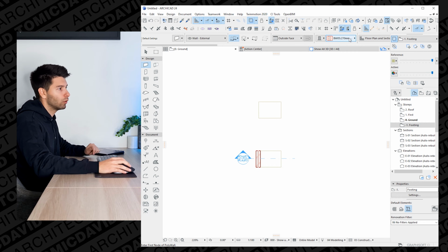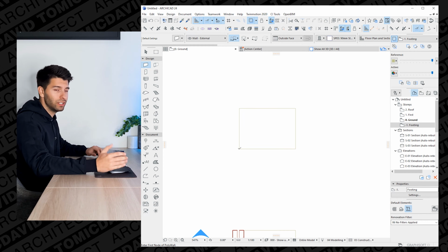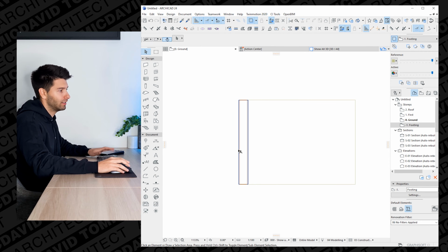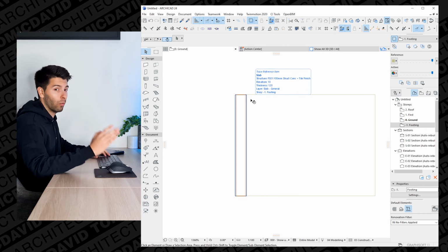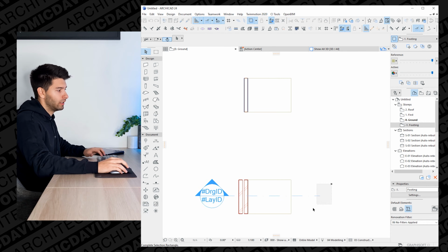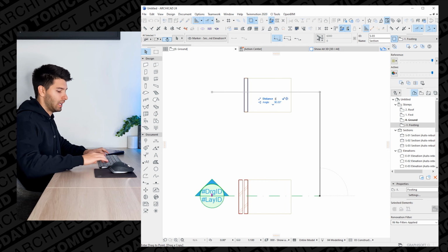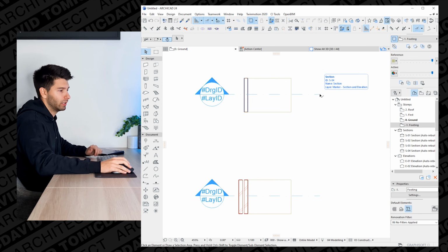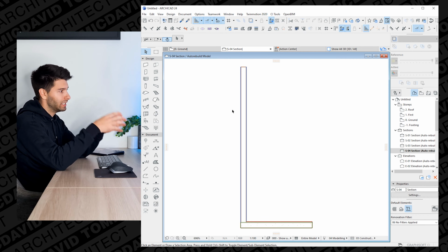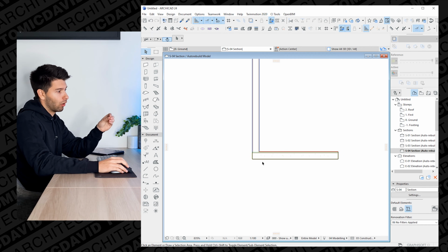I'm going to select my wall tool again, come all the way down to a 90mm stud partition. Now, just like we did with the brick coursing, we're going to click on the internal, press the P button to flip that entirely, and now we have our one single stud frame sitting on top of that concrete footing. Now I'll highlight this section, click it once, click the Control button, and drag that section up 3 meters to duplicate it. Right clicking on it, similar to what we did before, we can open in current view settings. So now we're looking at the beginning of our timber frame construction, connecting to our actual concrete floor.